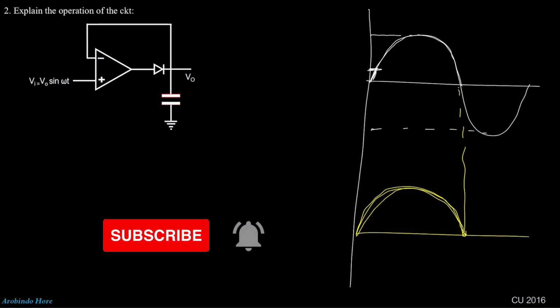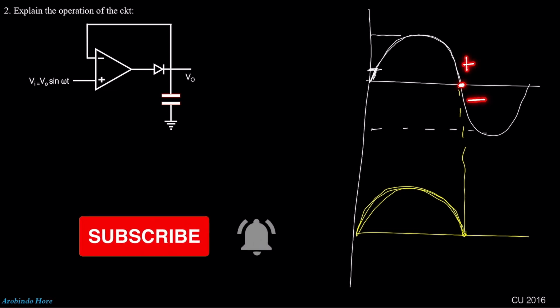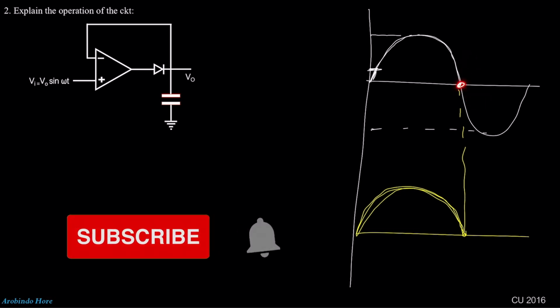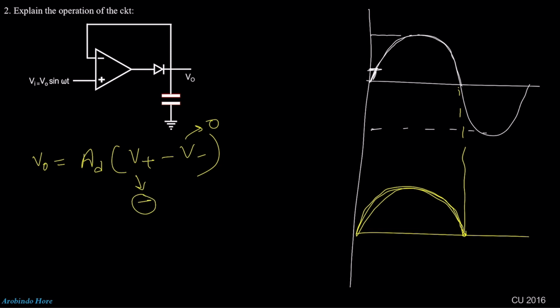For the negative half cycle, the input now switches from positive to negative. That means the value of Vi at this instant will be negative. Here the formula is V0 is equal to A into V plus minus V minus. Here V minus is 0 as I didn't give any input, and V plus is negative.